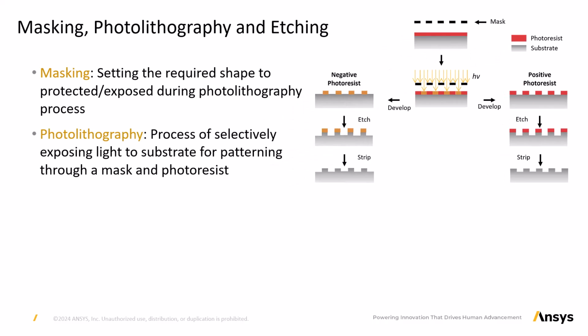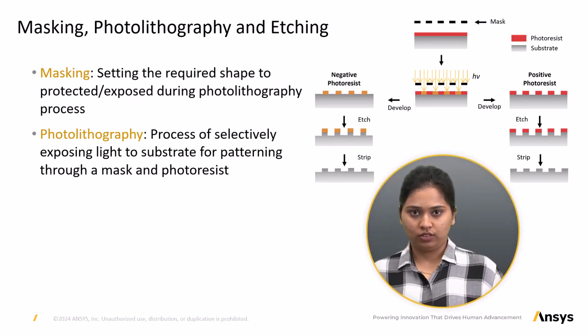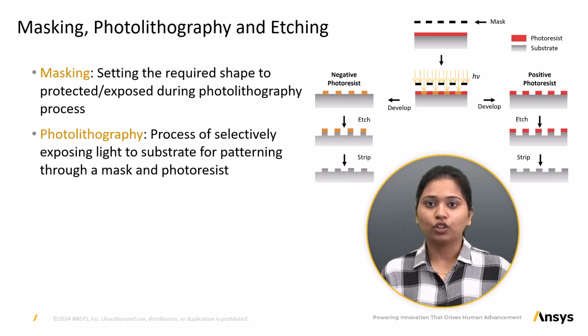Photolithography. When exposed to or covered from light, the photoresist becomes a soluble material in a special photoresist developer solvent and can be dissolved. The photolithography process applies light on the photoresist on the silicon wafer so that, depending on the type of photoresist, appropriate geometries of the design are covered with photoresist before etching.